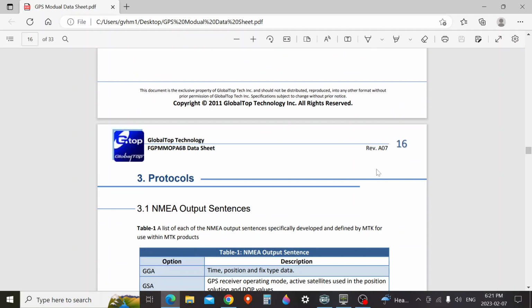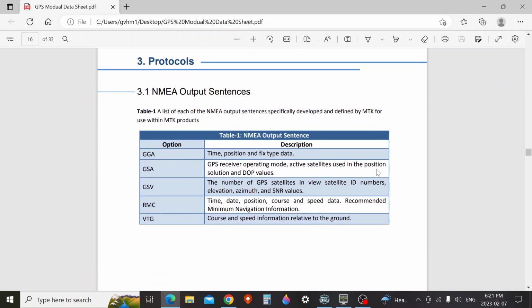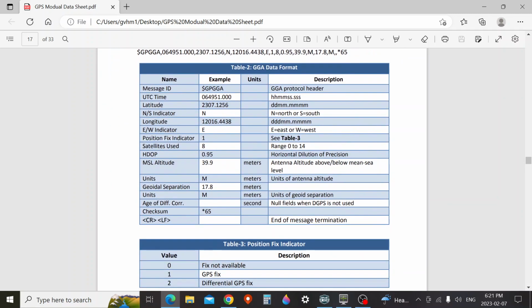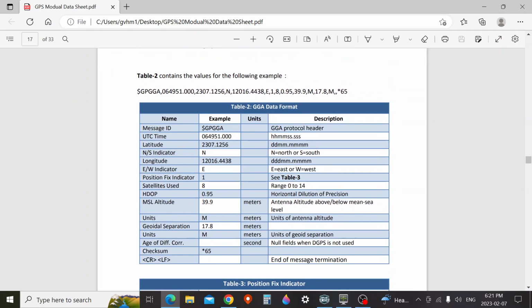Okay, so this tells you the protocols of the way the data is sent. Out of the gate, the first stuff that comes through is right here: dollar sign GPGGA, and then a comma, and then a bunch of data. This tells you exactly what you're getting, and as you remember, we just read the first two, the dollar sign and the G. Kind of cool, eh? Did that by hand. But if you continue to read, you would have found a P, and then a G, and then a G, and then an A, and then a comma.